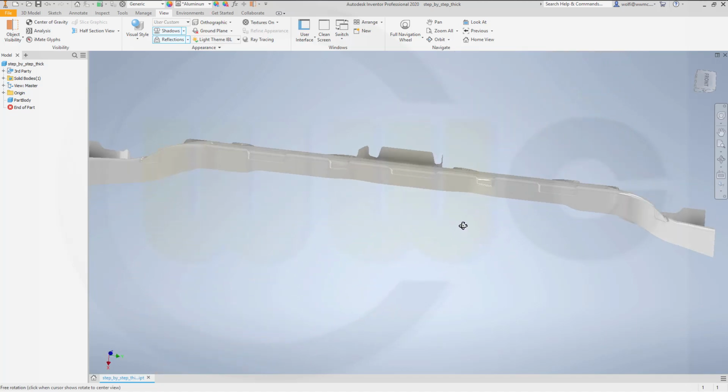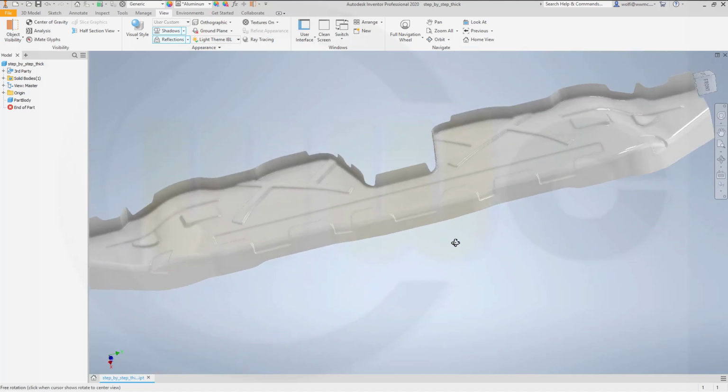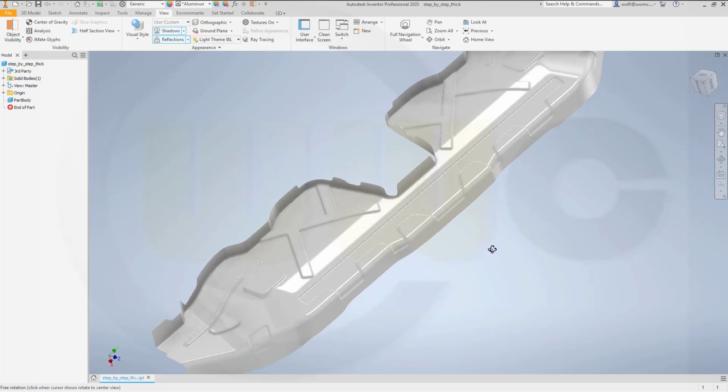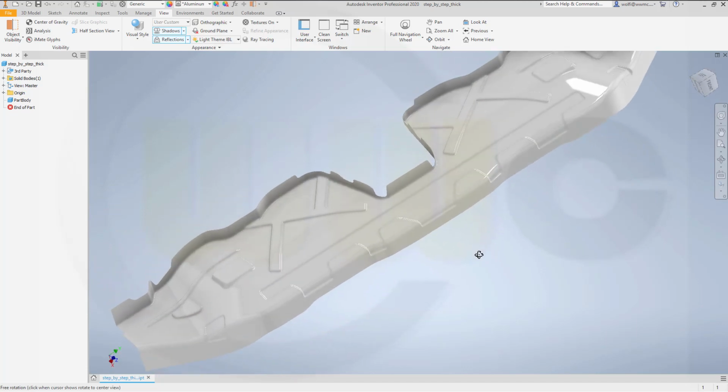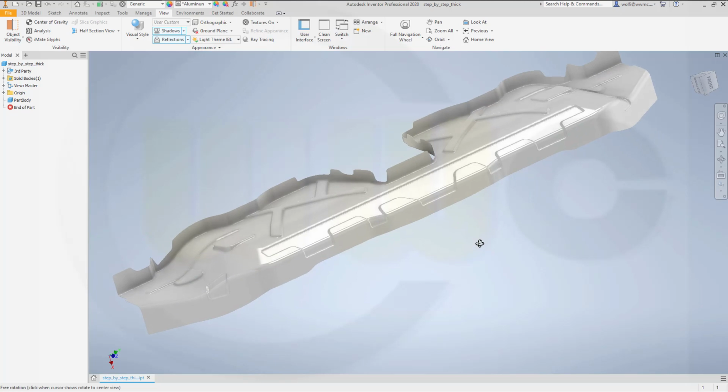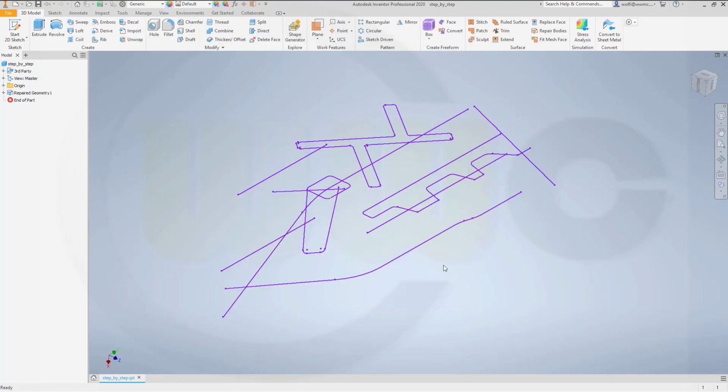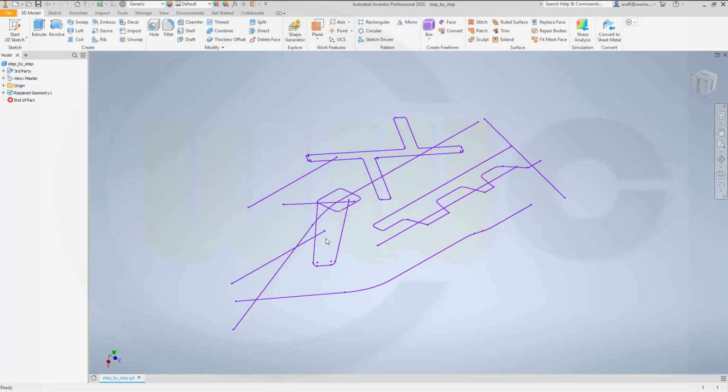I want to do that crossbeam exercise now in Inventor. Kind of similar to the Fusion version, but in Inventor we have at least a ruled surface command. So let's have fun with Inventor. In order to use those curves which I imported with the step file, I have to do a whole lot of 2D sketches, because the Extrude only works with 2D sketches, not with 3D curves.